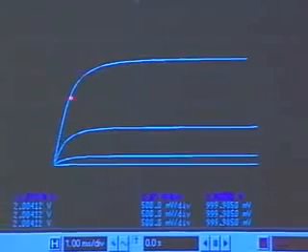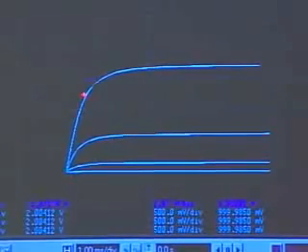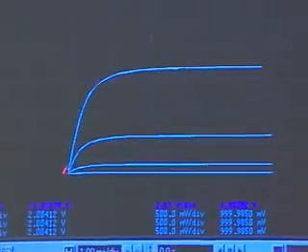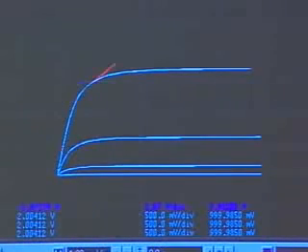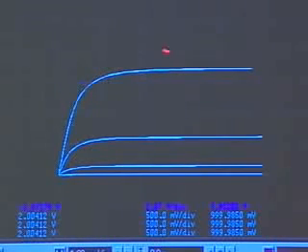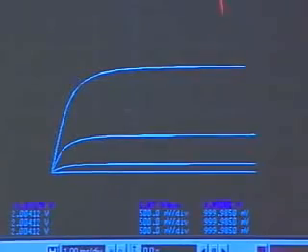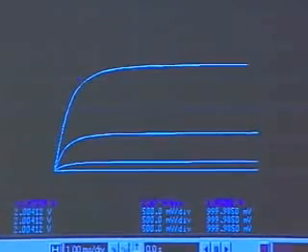In the beginning, I hid the right-hand side behavior from you and showed you just the resistive behavior out here. When I increase VDS to be much larger, the curve saturated and I got the saturation region operation of the MOSFET. And notice, as I increase my value of VGS, the saturation current also increases according to a square law behavior.